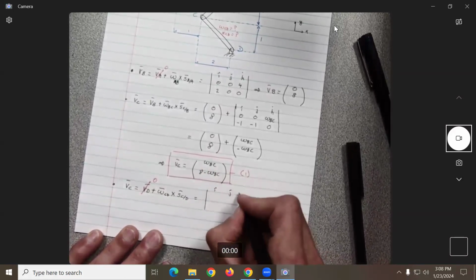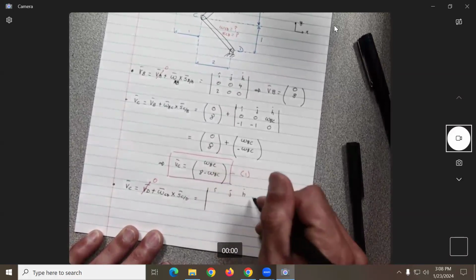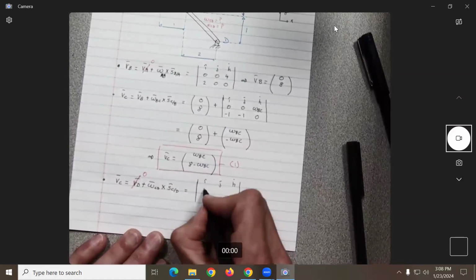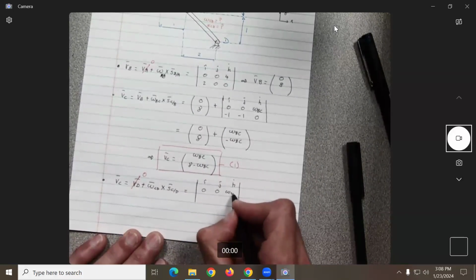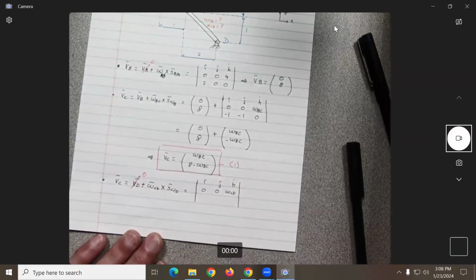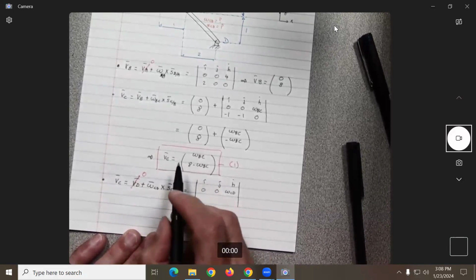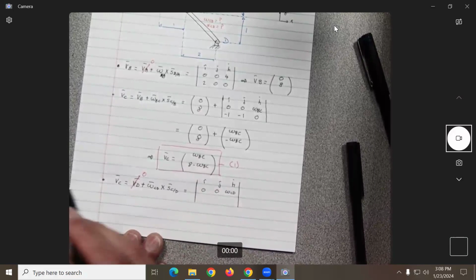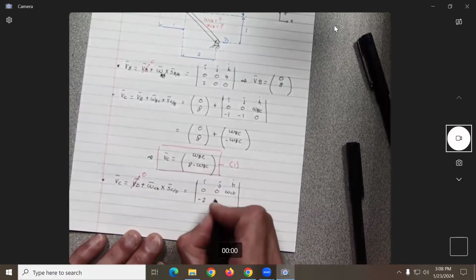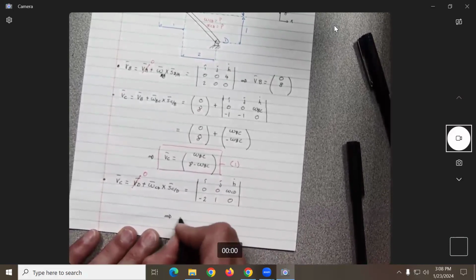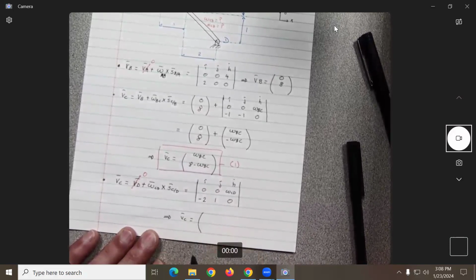So we're going to get over here what? IJK. I mean, you see that today you're already doing a bunch of cross products, no? And we're not even done yet. So, okay, this will be what? Do we know omega CD? No. So we put here omega CD. Next, what is the position of C with respect to D? Negative what? Position of C with respect to D. Negative 2, 1, 0. So this is going to give us what? The second expression for the velocity of C will be equal to what?